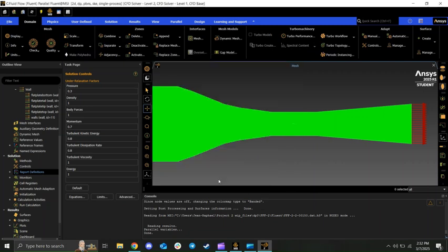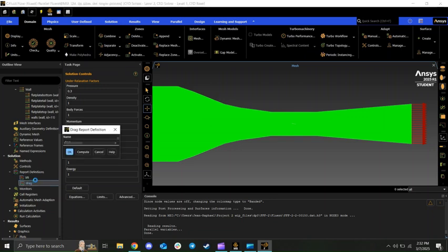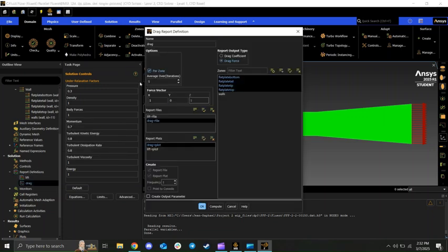So you would pull that up, pulling up the drag. Here's what would appear. So making sure drag is along our X line, the drag is horizontal, and then comes out to drag file, drag plot. And then here, ANSYS is a little finicky when it comes to finding the drag coefficient directly.